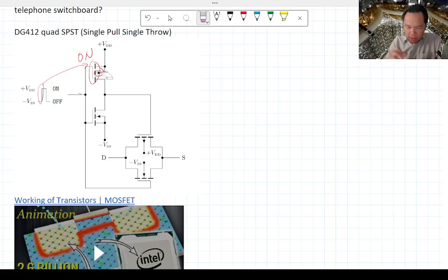Okay, so that means these are connected together. So when this voltage goes from VSS to VDD to digital, right? Basically think of this as a solid wire. Since this is a negative edge trigger, this doesn't do anything, so it doesn't get connected. This is also a negative edge trigger, so this doesn't get connected either. But you'd have the connection up here, from here all the way down to here. And now this is pointing out, so this is also a positive edge, so that gets connected. So what happened is that the data basically gets sent from D to S, okay?